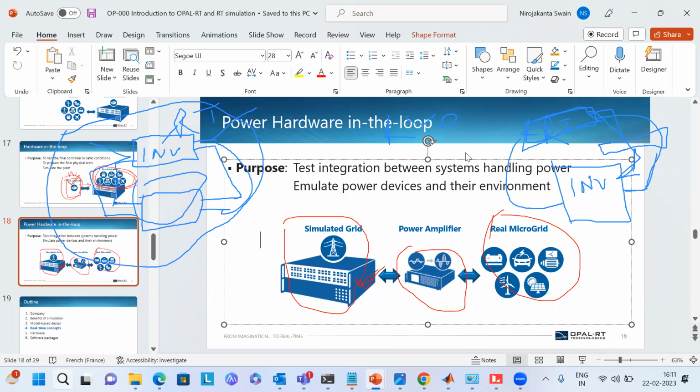One more question is there, sir. What is the maximum sampling time of Opal-RT in fixed type? Yes. In fixed type, it's always running with a fixed type solver. For maximum sampling time, you can go up to 1000 milliseconds, no issue. But we always recommend running our model at the minimum sampling time for accuracy of the model.